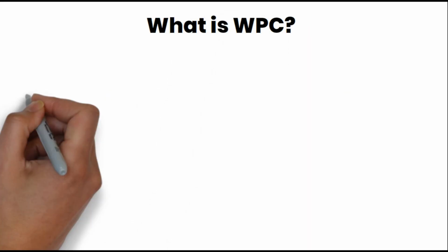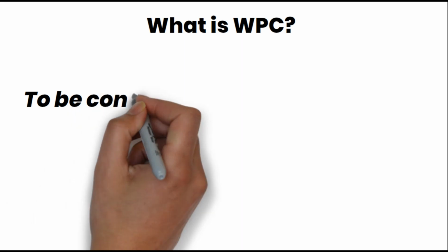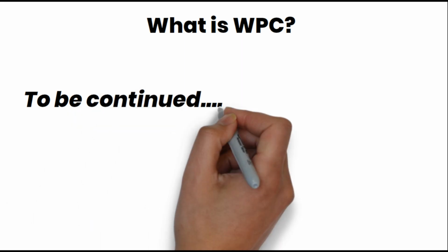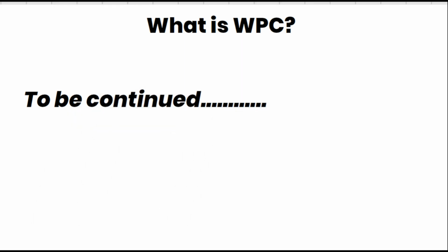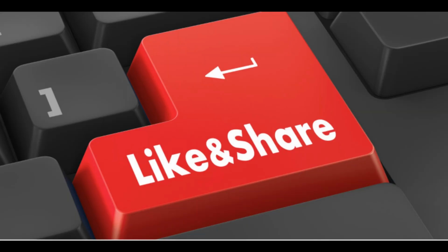Whenever you purchase a plywood, just go for a reputed brand or a quality brand, and just check the quality of the plywood and the grade of the plywood, and you can even ask for a manufacturer test certificate if you require, and this will give us a clear picture of what is being used in that particular plywood.